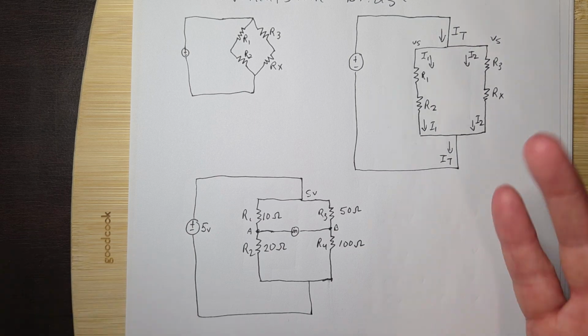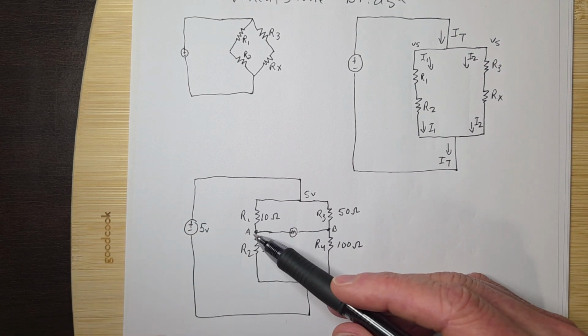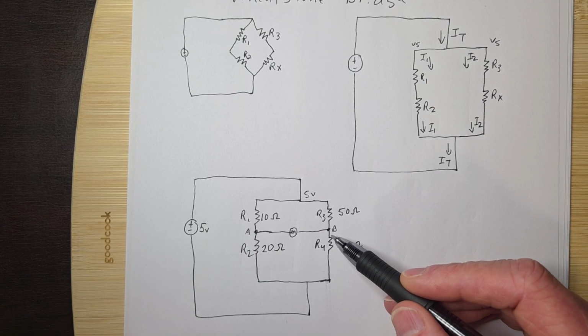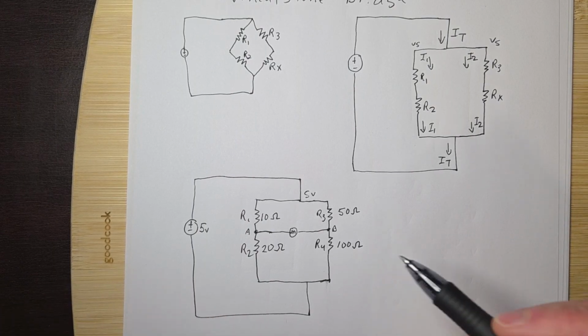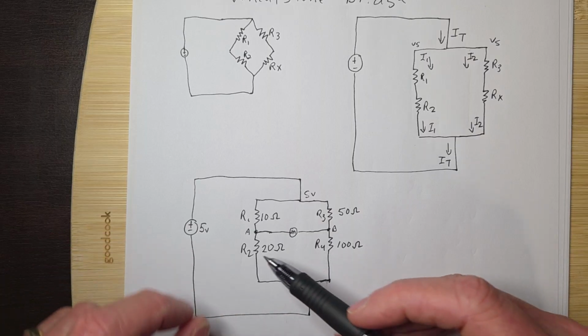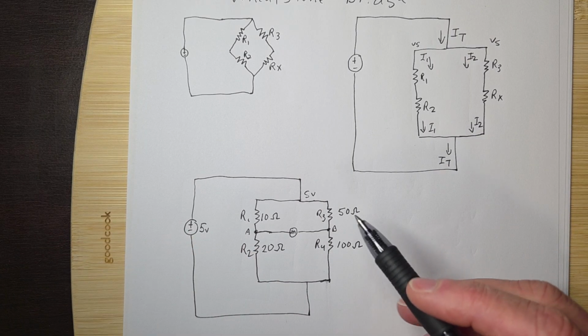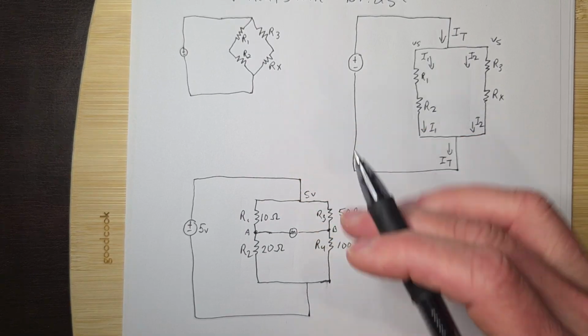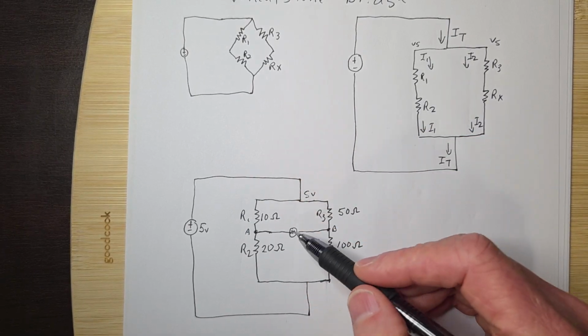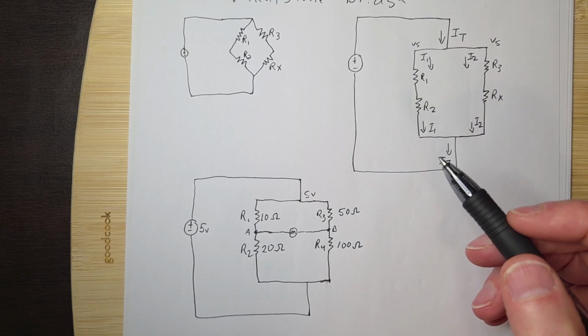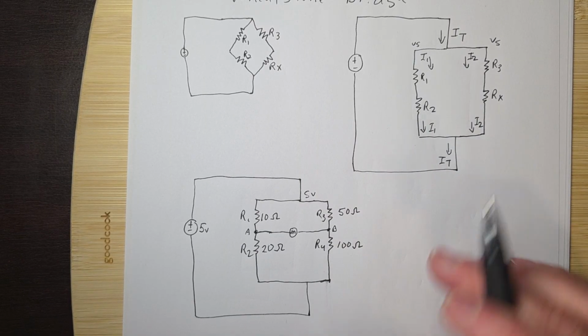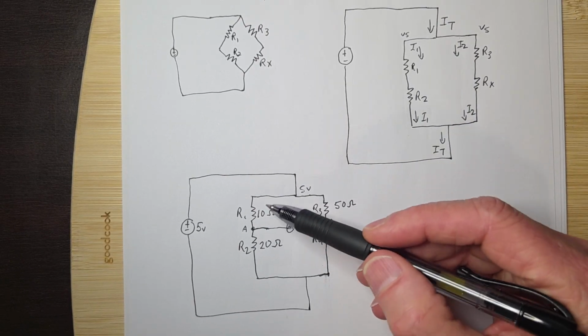Or let's say, just as an example, this was 3.33 volts, and this was 3.33 volts, then the potential difference is 0. If it was maybe 3 volts and this was 1 volt, then you'd have a 2 volt difference, and then current could flow. So that's the power of the Wheatstone Bridge. As long as it's balanced, this will always read 0. And we'll explain why it being balanced is a good thing. But just remember, this is just a ratio.